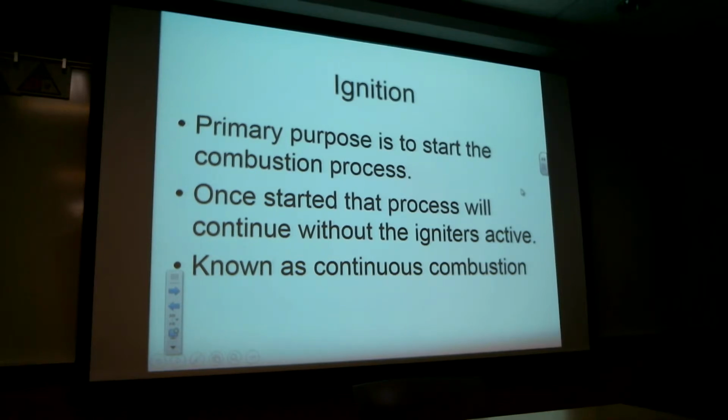So if an igniter is good for, say, 3,500 hours of operation, that's 3,500 hours of operation, not just being flown around the skies for 3,500 hours. If this thing runs constantly, you may cut down the life of that igniter to maybe 500 or 1,000 hours of operation. What's a turbine igniter cost?